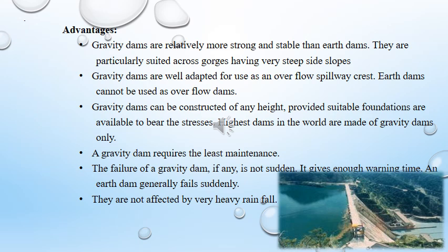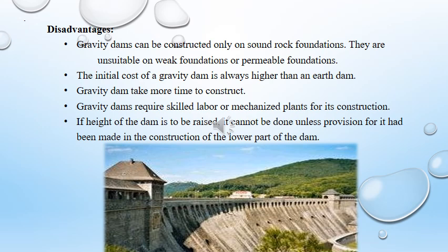So, these are some advantages of gravity dams. And the disadvantages of gravity dams: these dams are constructed only on sound rock foundation, and they are unsuitable on weak or permeable foundation.